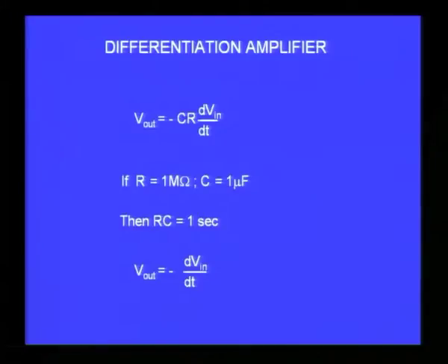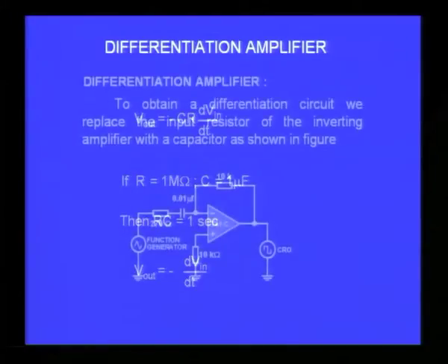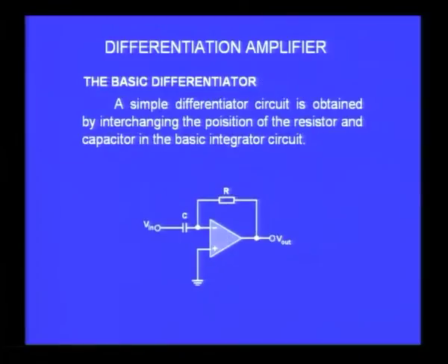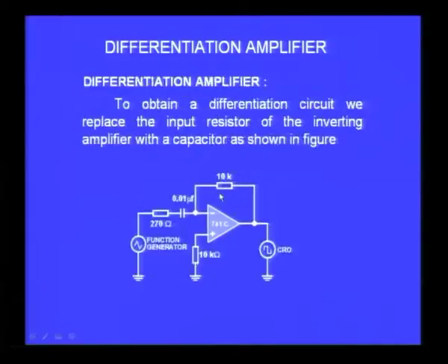Right. Now I will explain to you about the circuit. So here this is the basic circuit which involves one capacitance and one resistor, but that is slightly modified here for a very specific range of frequencies in the range of 1 kilohertz. And so you find I have used a capacitor whose value is 0.01 microfarad and a feedback resistor which is 10K, and I have also used a resistor here which is a very small one, 270 ohms.